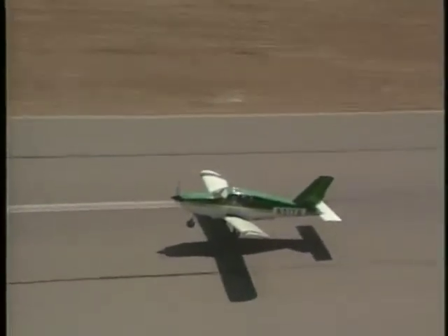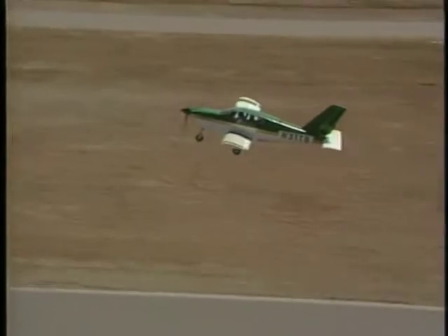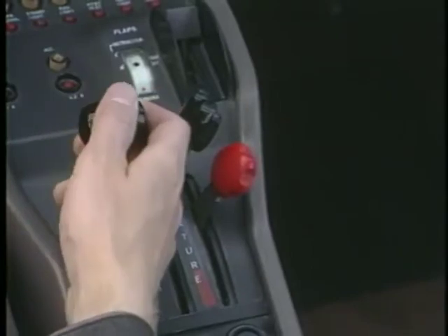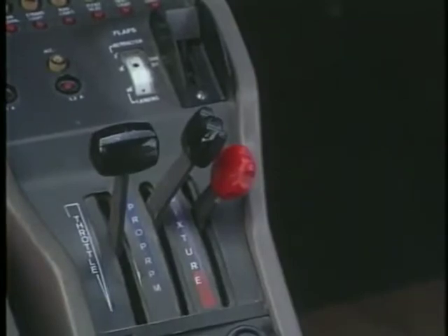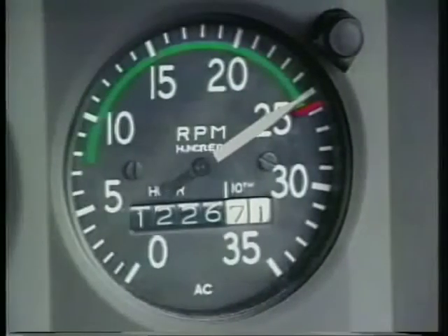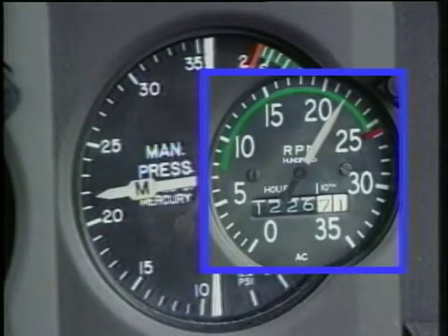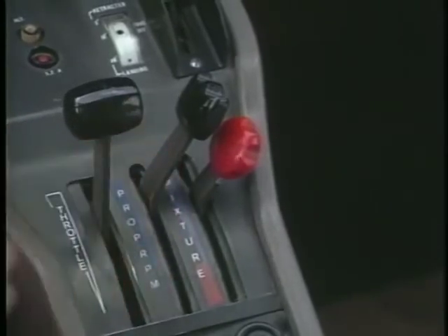Another way to keep from damaging the engine is to follow some basic procedures when decreasing and increasing engine power. For example, when reducing power, first decrease the manifold pressure with the throttle. Then decrease the RPMs with the propeller pitch control. It's important to note that as propeller RPM decreases, manifold pressure increases slightly. Therefore, to avoid excessive manifold pressure for a given RPM, it's best to initially reduce the manifold pressure below what is desired. Then, after the RPM is set, adjust the throttle to the desired setting.